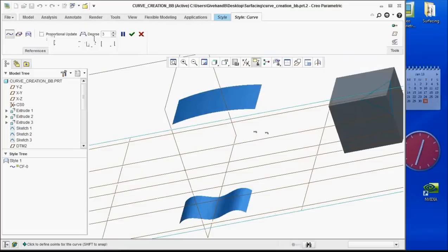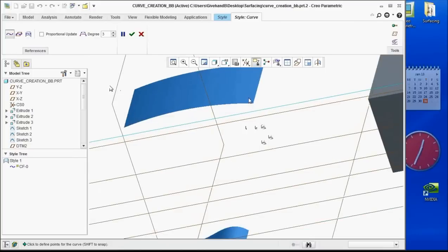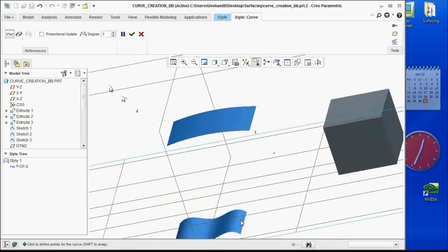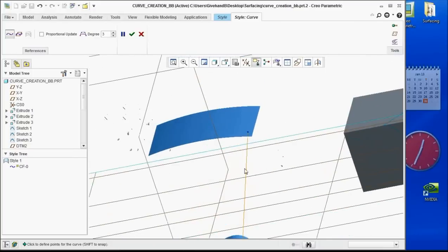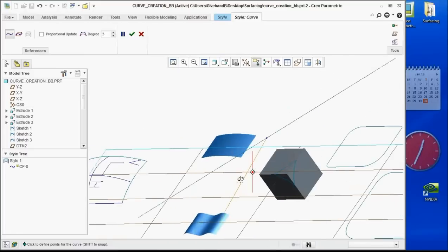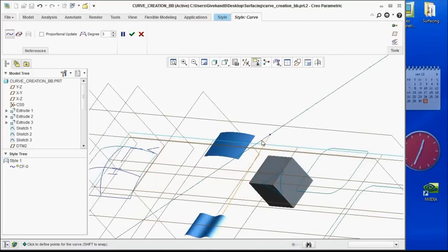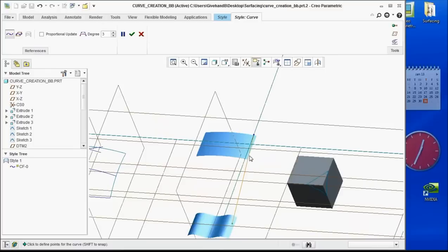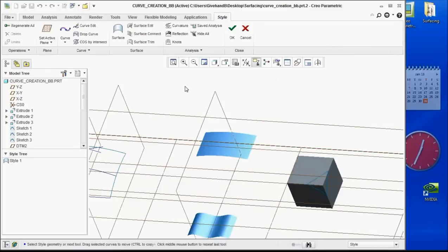Now, when you create a curve in the ISDX tool, you have essentially a 3D curve, or what is called a free curve. You have a planar curve, which is a 2D curve, and then you can drop a curve on a surface just as far as just picking points on the surface, and it drops a curve on a surface. And so what I'm going to do here is I'm going to say I want to create a curve, and I'm going to pick this surface, and I'm going to pick right about there, okay? Now, what's interesting about this is notice how it did that, okay? So if anybody's ever done this and they've done this right here, you have to kind of understand how this works. And so let me back out and let me do it again.